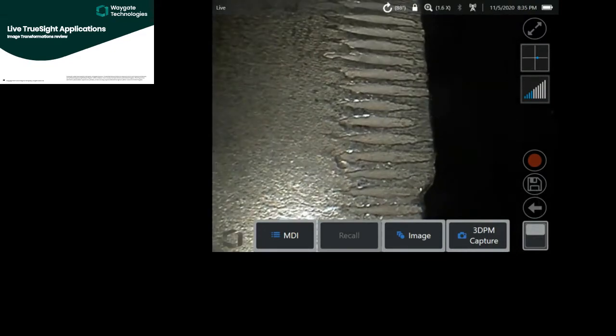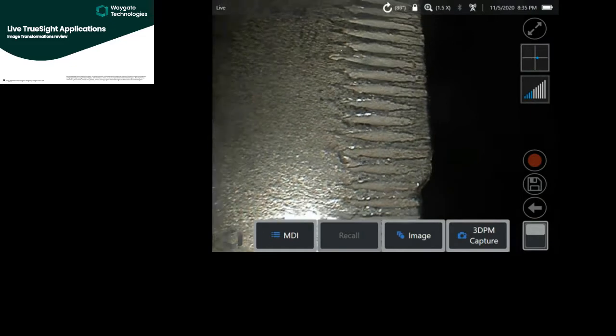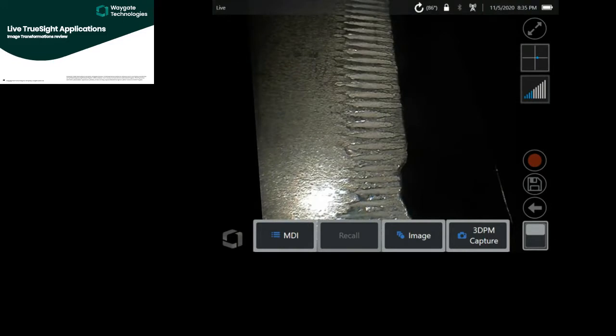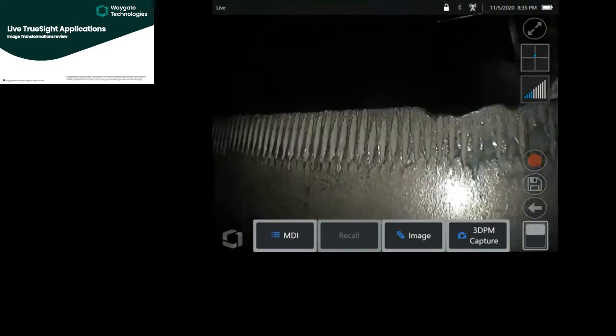Maybe I'm used to looking at turbine blades vertically oriented on the screen. Or maybe the engine maintenance manual gives you a picture and says, check the blade this way. I can now rotate my blade to look just like the picture on the manual. So there's some tools that you can use for validating if things look like what the manufacturer says they're supposed to look like.